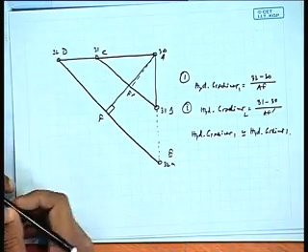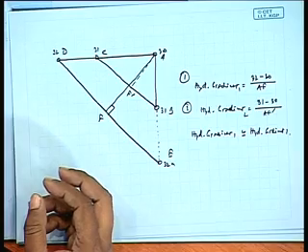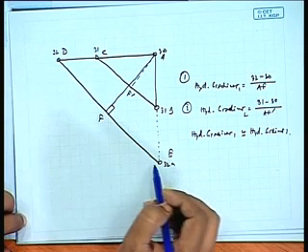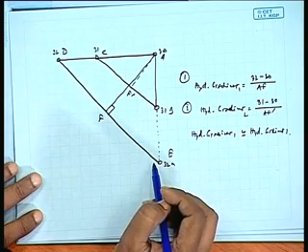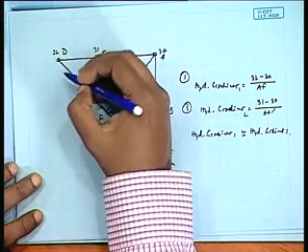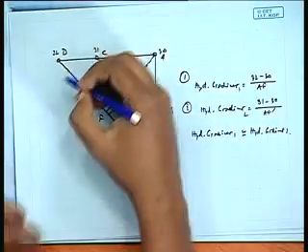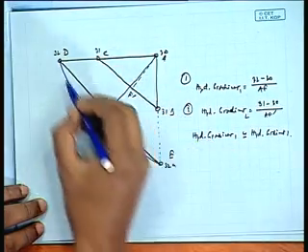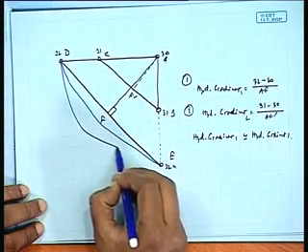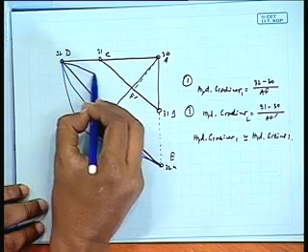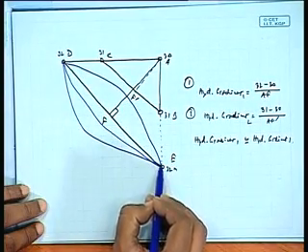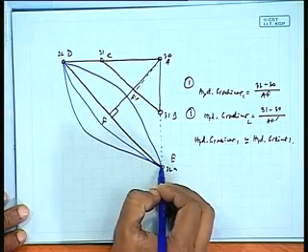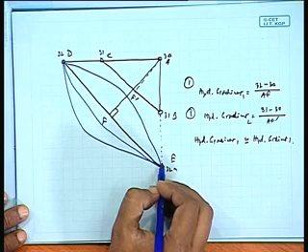Now, the question is, having said this, is there always an equipotential line? Or is there an equipotential line which necessarily has to be a straight line? It is not. But in such cases also, even if the equipotential line may be like this, or like this, or like this as well, generally it leads to somewhat closer results. So you can see the equipotential line is not necessarily a straight line.